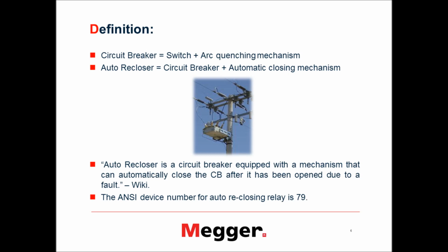The Autoreclosure is nothing but a circuit breaker with an automatic closing mechanism. So according to Wikipedia, Autoreclosure is a circuit breaker equipped with a mechanism that can automatically close the circuit breaker after it has been opened due to a fault. So whenever there is a fault, the circuit breaker opens or isolates that part of the circuit, and the auto-reclosing mechanism will automatically close the circuit breaker and restore the normal operation of the system.